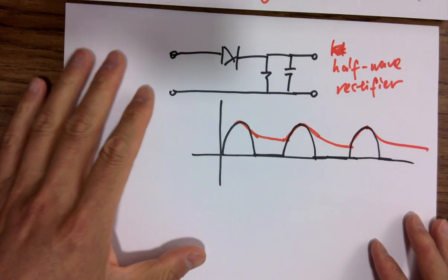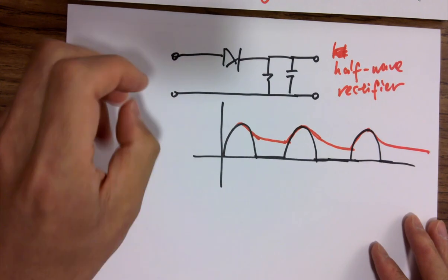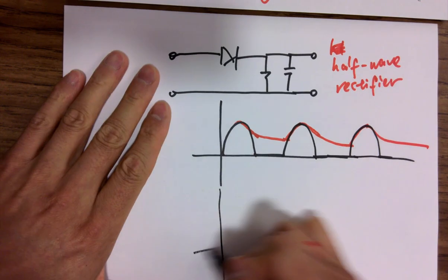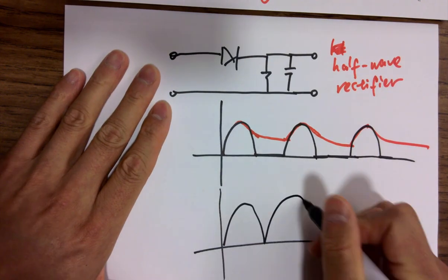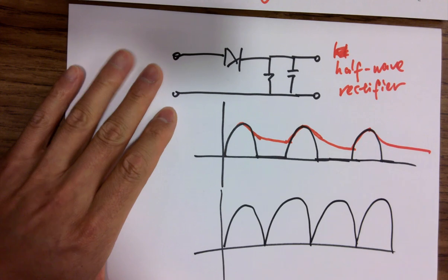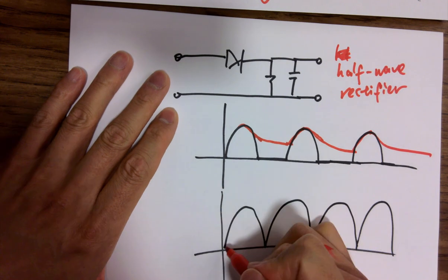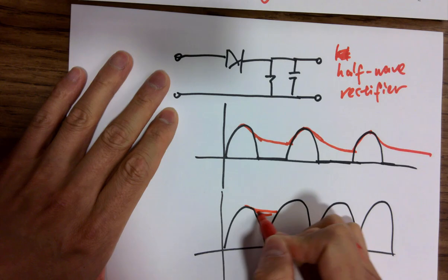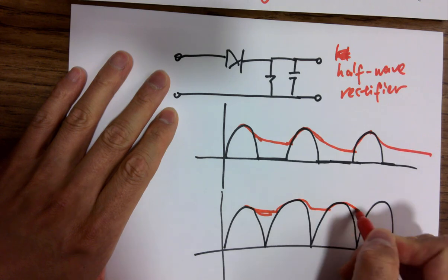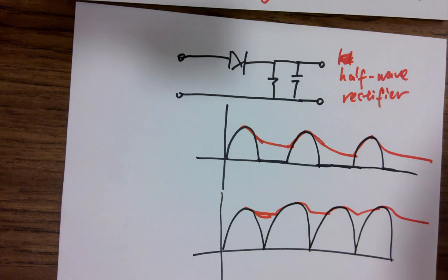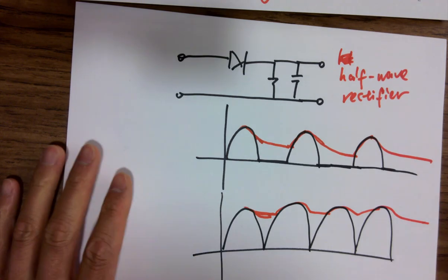It's the analog stuff. So the full wave rectifier will be able to reduce this even further because the full wave rectifier is giving you continuous bumps like this. So you have less low voltages, and eventually it's able to reduce the amplitude of the ripple a little bit to make it more stable, right? So that's a full wave rectifier output.